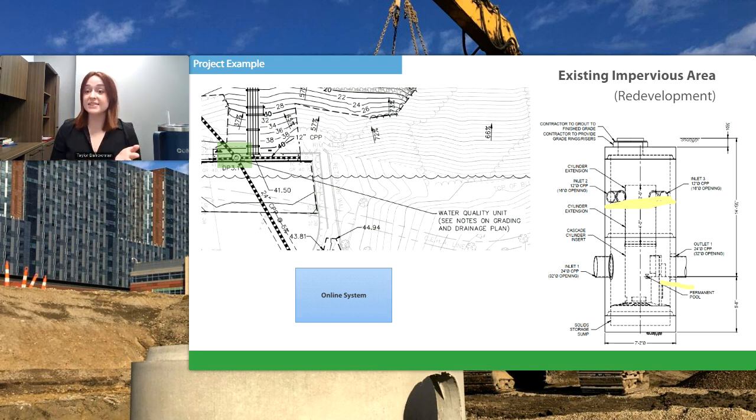But in instances where you don't have the cylinder extension, if you can't have a depth that great, while this was the right solution for this project, it might have been more feasible to look at a vault structure. It might have been better for your site if we looked at an upstream structure to collect those internals and collect that water, and then at a more reasonable outlet to inlet drop, or inlet to outlet drop. Water doesn't go uphill. You can then utilize an HDS unit with just that smaller drop required.